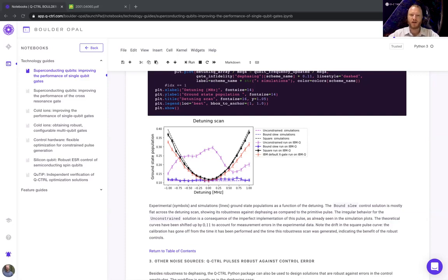this dephasing error. We have also independently measured the amount of drift on the qubit as a function of time over the day. We typically see drifts up to 0.25 megahertz. This indicates that if you used Q-Control's pulses for X gates, your algorithms would run more accurately for longer during the day. We are continuing to work on further results on randomized benchmarking and homogenization of errors across the chip. Stay tuned for more results from Q-Control on those topics.